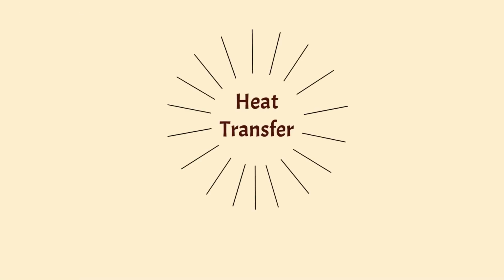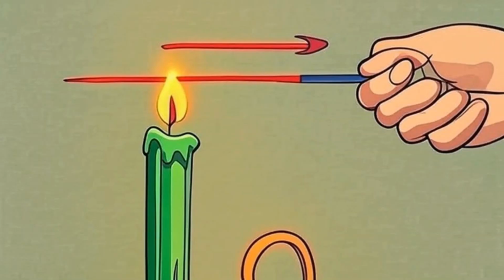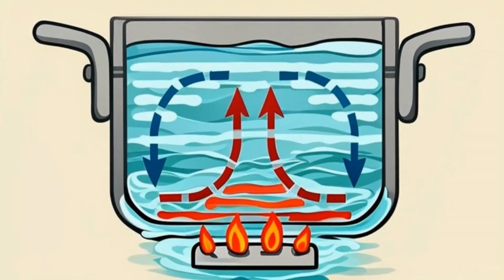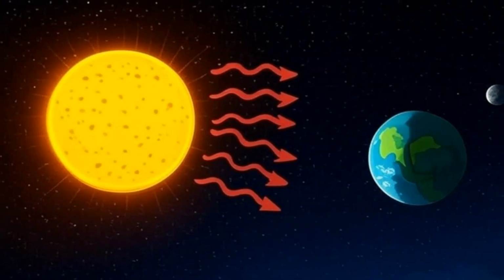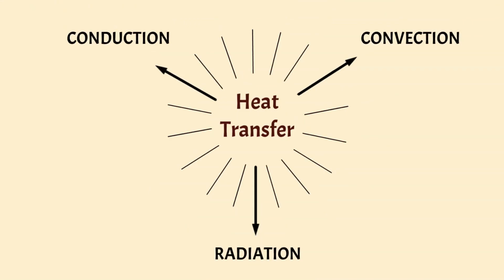Okay, so much for rate of heat flows. Let's now address the three ways of how heat can be transported from one object to another. The first is conduction. This occurs primarily in solids, but also, to a lesser extent, in fluids. The second is convection. This only occurs in fluids, that is, liquids and gases, and not forgetting supercritical fluids too. The third is thermal radiation. This does not require a medium to transport the heat from one object to another. Together, these mechanisms form the holy trinity of heat transfer.